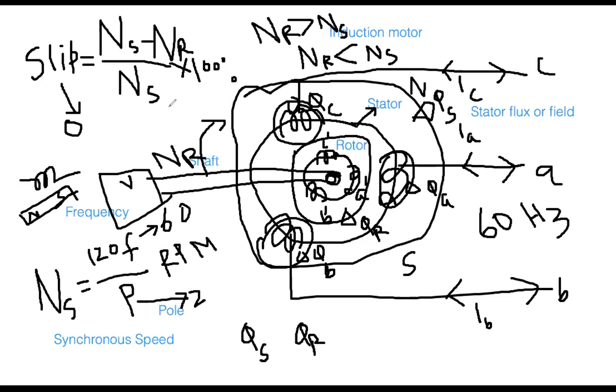On the other hand, everybody see, at the beginning of the operation, when the shaft was not rotating, when you applied the voltage, there was a three-phase magnetic field. That is fine. This means that in the equation you have Ns, but what was the value of Nr at that time? Nr value was 0 because the shaft had not started rotating yet. So what is the value of the slip in that case? Ns over Ns, slip value is 1. So everybody see that when the slip value is 1, the motor is not rotating, the shaft is not rotating. When the slip value is 0, at that time also your shaft is not rotating.